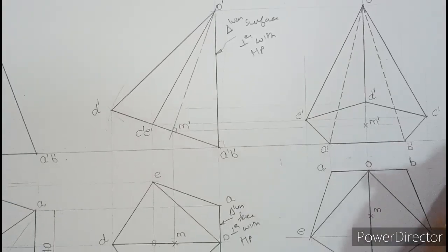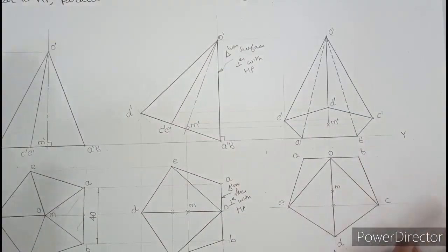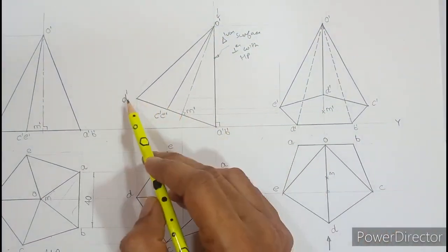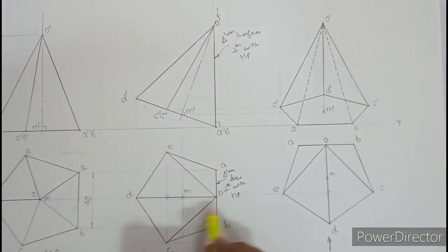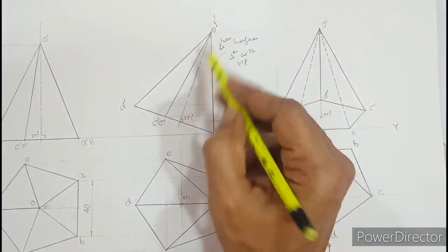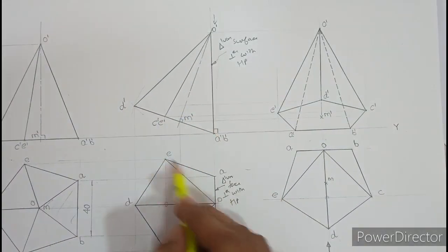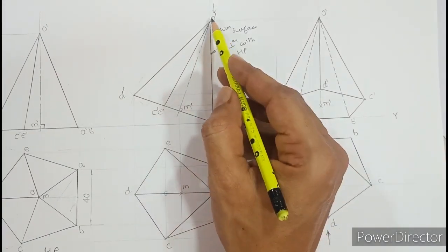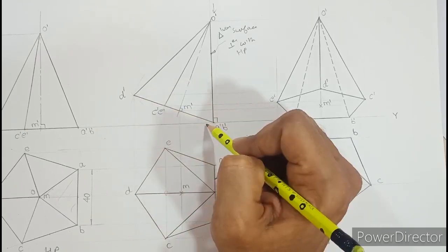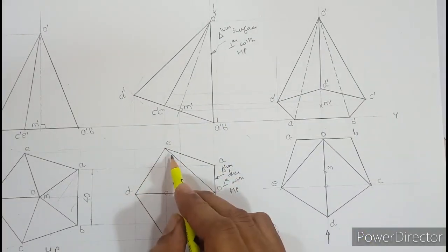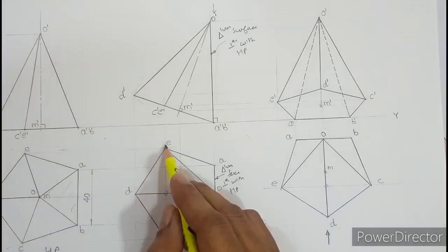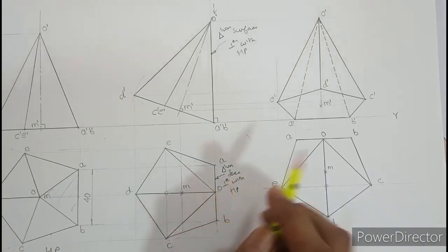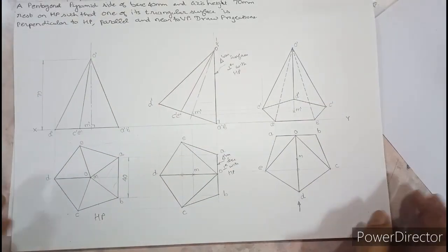Okay, so the turning point of this question was, if you look at the second stage top view, and if you switch on the bulb, you can see everything from D to AB. So here all the slant edges are dark. But the question arises, when you compare O with M, M is away, so the base has to be hidden. Then why is it drawn dark? The answer is, I agree that M is away, so the base has to be hidden. But there are no lines left to be drawn hidden because all the base edges are being joined to form the shadow or the outline of the object. So there is nothing left to be drawn hidden. Okay, so that is about the 3 stages for this question.